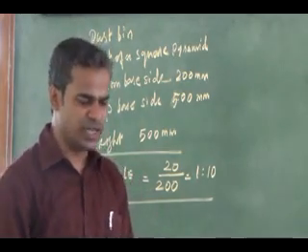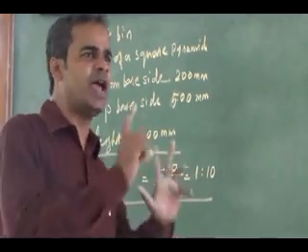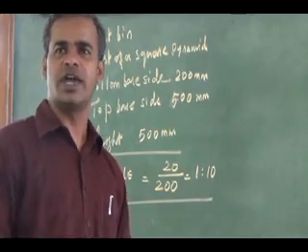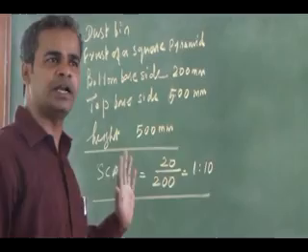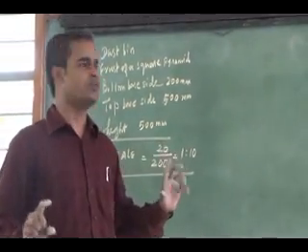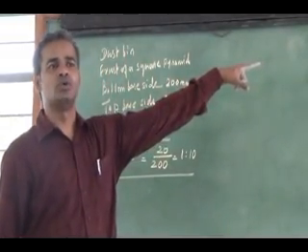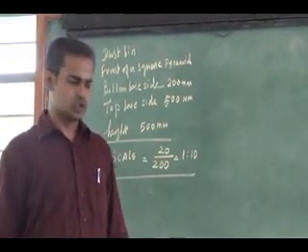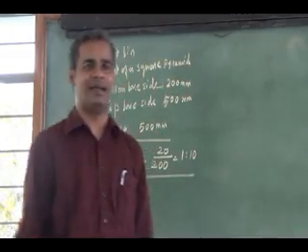Right. So you see, the orientation of the dustbin is not given. We just have to draw a development of a dustbin. It's a frustum of a square pyramid. It can also be a frustum of a pentagonal pyramid or hexagonal pyramid. Very simple, only if you are able to find out the true slant length. So in which orientation can I easily get the true slant length?